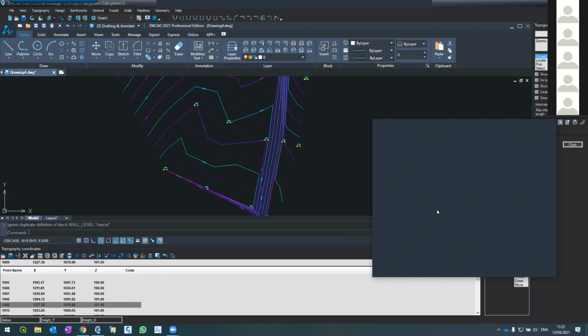Everybody, take the text file and place it somewhere. You can put it on your desktop. Go to ZWCAD Civil, start a new project. Let me write it down. 1, load the text file and place it on your desktop or somewhere else. It's not so important where. 2, start ZWCAD Civil. 3, file, new project.